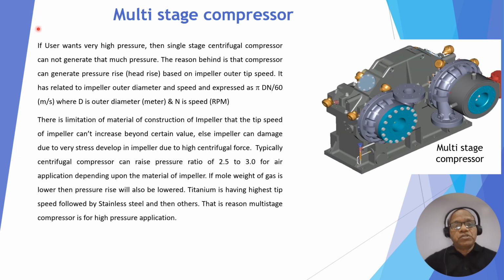Now the next question is why a multi-stage compressor is needed. You can see a two-stage compressor is shown here. This is the first stage, this is the second stage. One stage means single stage, another stage is similar to the compressor, so it is called multi-stage: one stage, two stage. The gas comes here, goes out, then comes here, then goes out. Of course, based on requirement, this high pressure, high temperature gas needs to be cooled down before coming to the second stage.